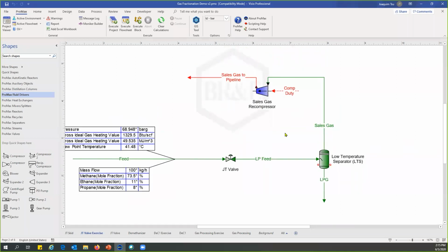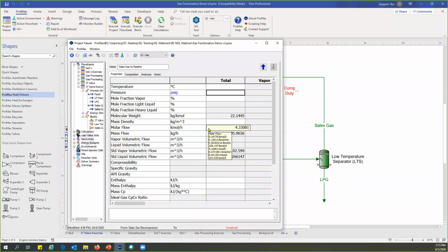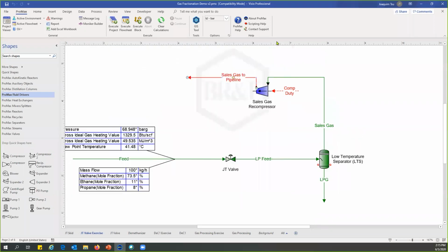As for the sales gas recompressor, we have 1 degree of freedom from the sales gas recompressor itself, and we have 1 more from an energy stream. Every time you see an energy stream, generally that means we have 1 more degree of freedom. So the first obvious one, I'm just going to say I will recompress it back up to about 1100 PSIG.